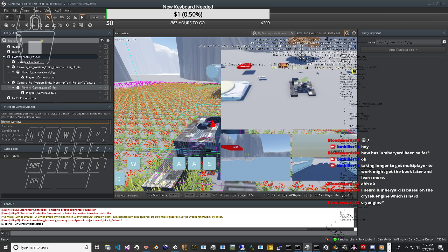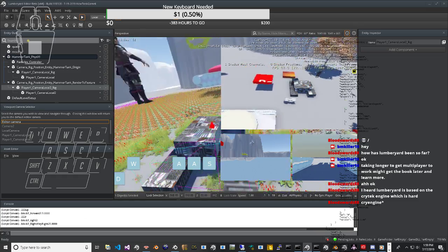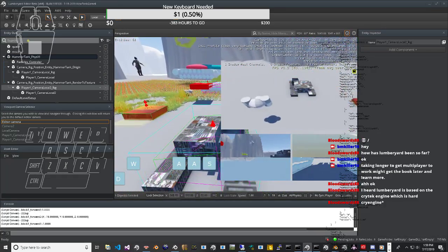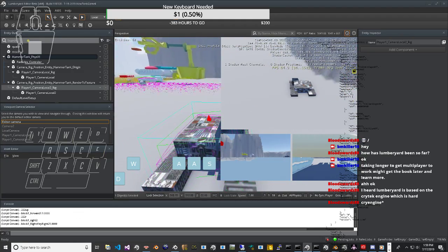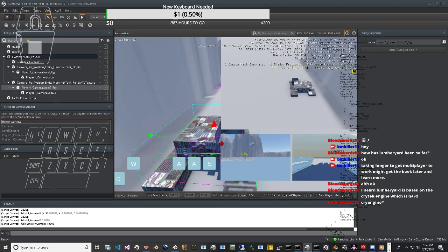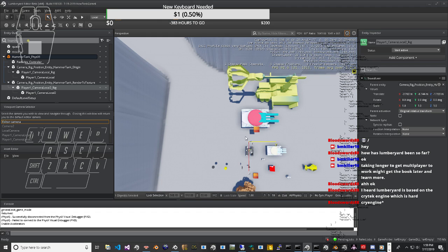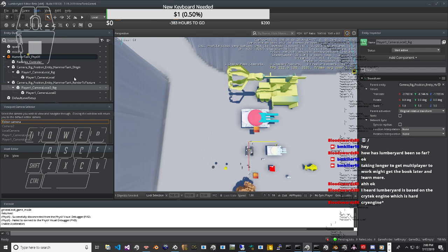Since wheel is tilted in Earth, relative to gravitational down, the load, Fz, on the contact patch, which we need for the magic formula, must be computed in wheel. It will be smaller than the total weight, Wi, by factors of cosine, which are obviously unity under the small angle approximation. At last, we can plot the magic formula. The horizontal axis measures slip angle, in degrees. The vertical axis measures lateral, cornering force, in newtons.